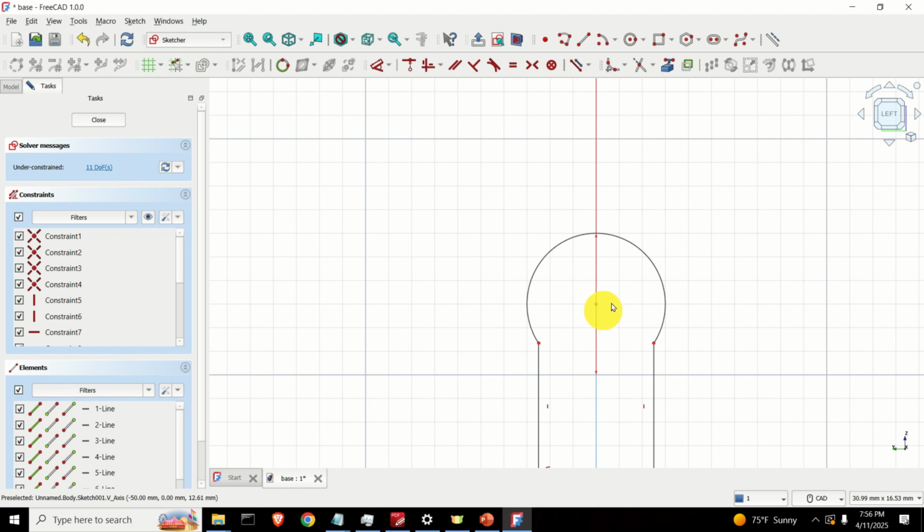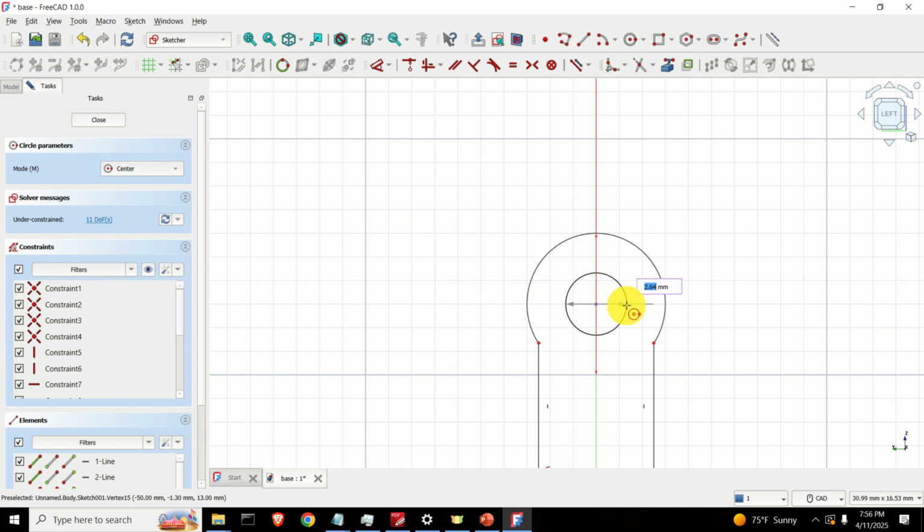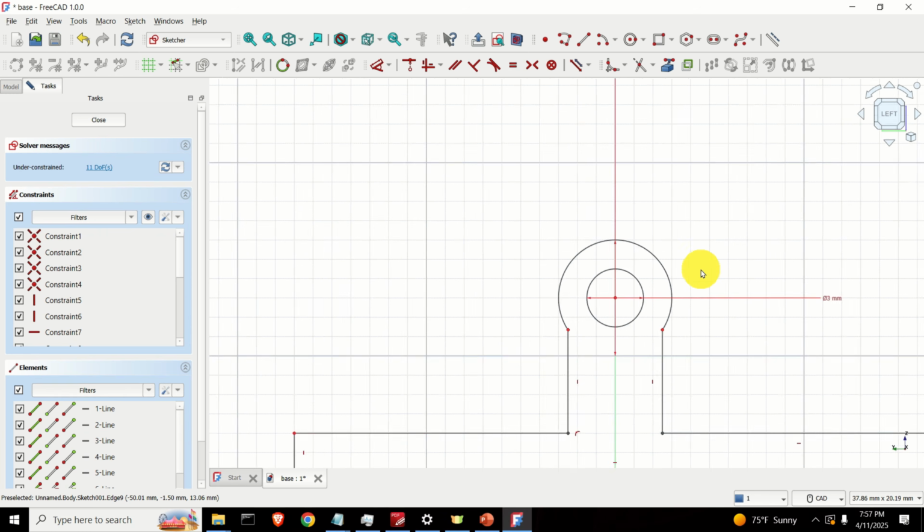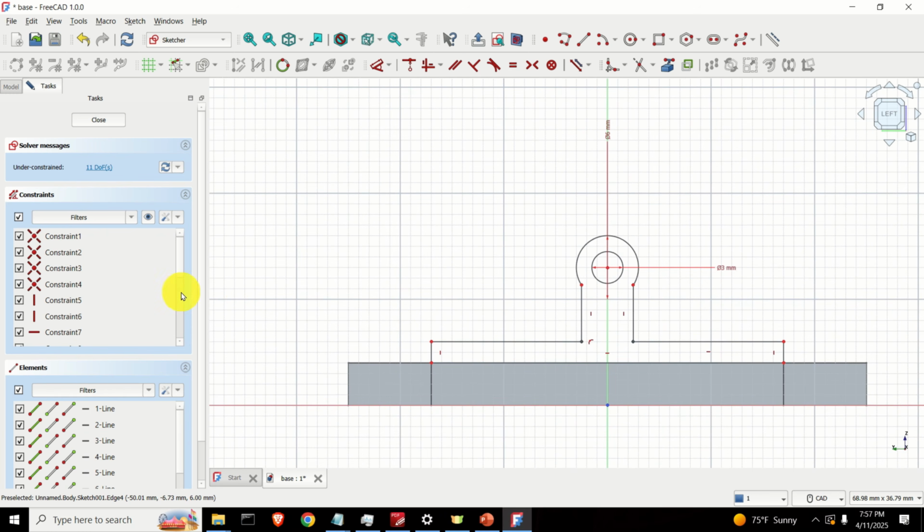Inside of this hollow cylinder you will have the slider coming in. So let's do that. Again, click here on create circle by center, click here, and over here we need to be precise. First of all, let's see one very important thing. What is this thing over here? It's the diameter. Here, I'm going to specify the diameter 3. And keep in mind and remember this number, since the slider diameter should also be 3 millimeters. Do the right click, and now we have the support for the slider.